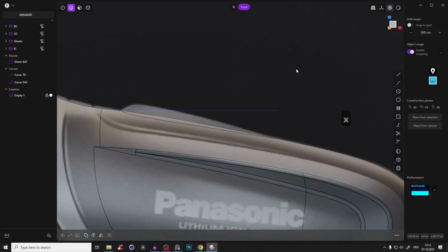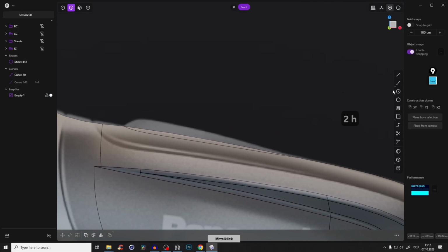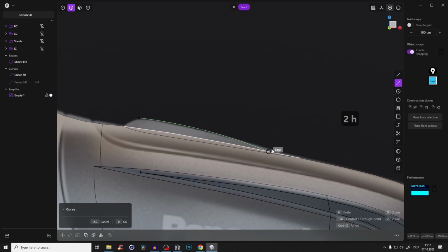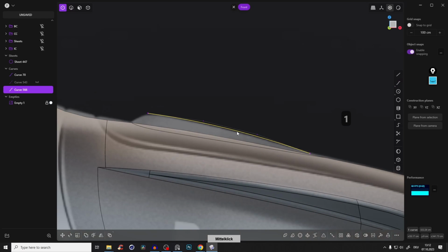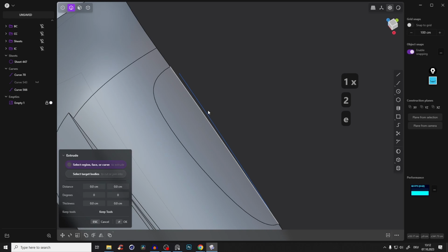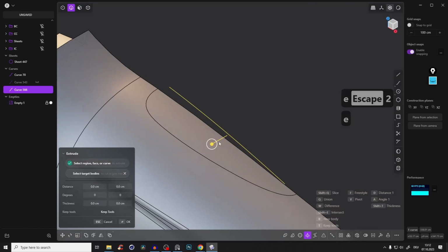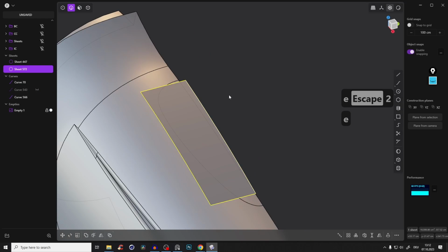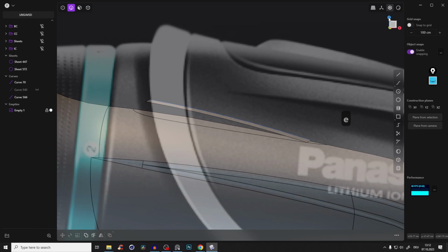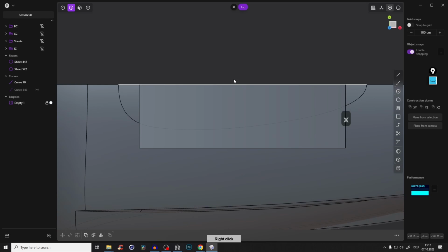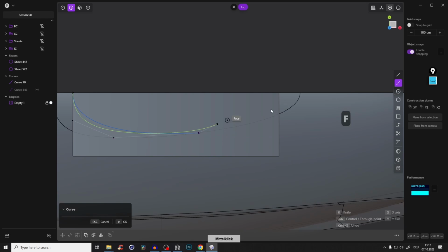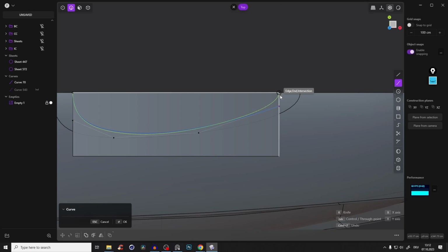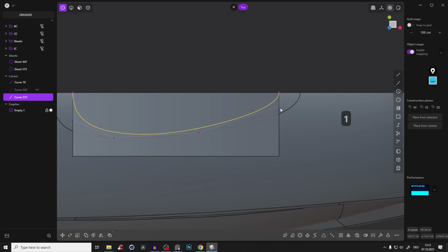And what we want to do now is again go to the front view and hide this curve and just follow again this shape. Let's go to somewhere here. Again, we are just following the shape which we have. And now just select that curve and extrude that here inwards, because we need basically the top now. So we have to cut again a piece out. So Shift F, control point curve, drag it along the edge so it's tangent, and again create some extra points. Shift click at the edge, or you don't need shift click, and so this will be tangent here.